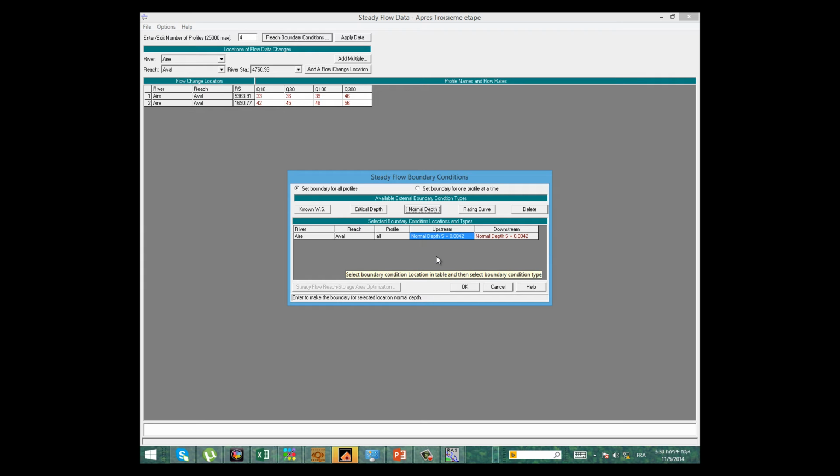Because of the decrease in velocity, some of the sediment carried from upstream will be dumped in this area, because the flow is less and the water flows gently. Then through a long process, those dumped sediments build up the side banks, and the channel becomes narrower and narrower, until it forms a velocity called a non-scouring and non-silting velocity.